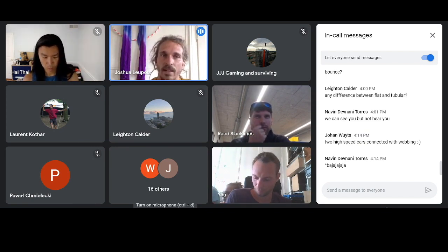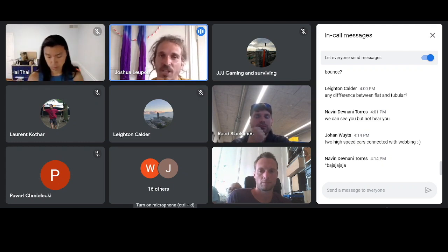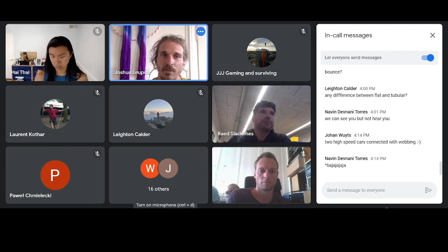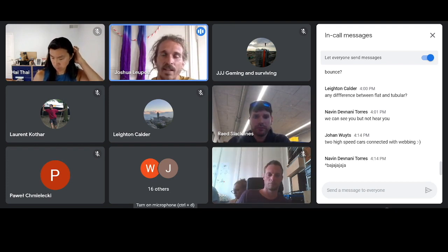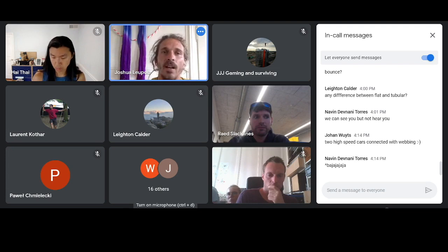And you also see what the peak forces are, and then you just have your video with it, and therefore you just need to find a method to match up the two devices with each other. I guess it's possible to do this electronically directly. Otherwise, you can also do it manually if you make one cycle much slower, and then you know exactly, okay, here I really start the testing, and that's how you can synchronize it.